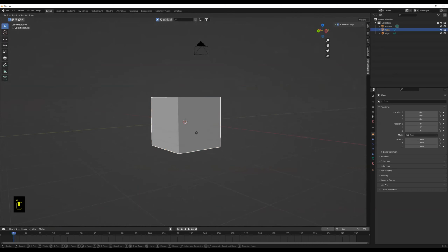Well, to select the face, you have to go up to the top next to this edit mode and make sure you have the rightmost one selected, the face selector. And then once you have your bottom face extruded here, we're going to scale that out. We're just going to use the base scale function. We're not going to use any of the axes. We want to scale it out all the way.